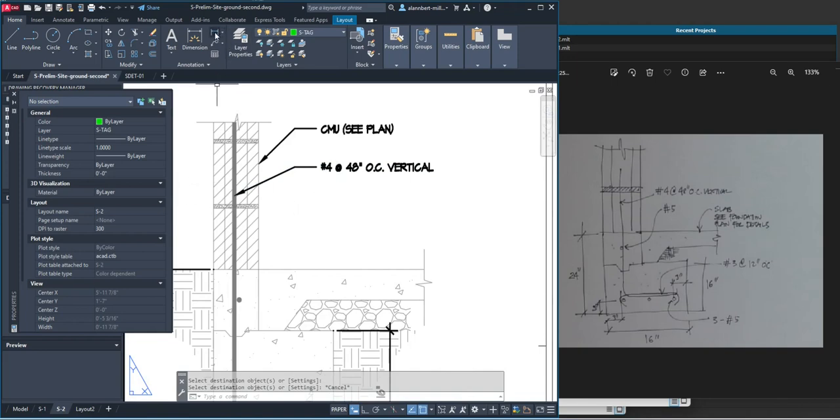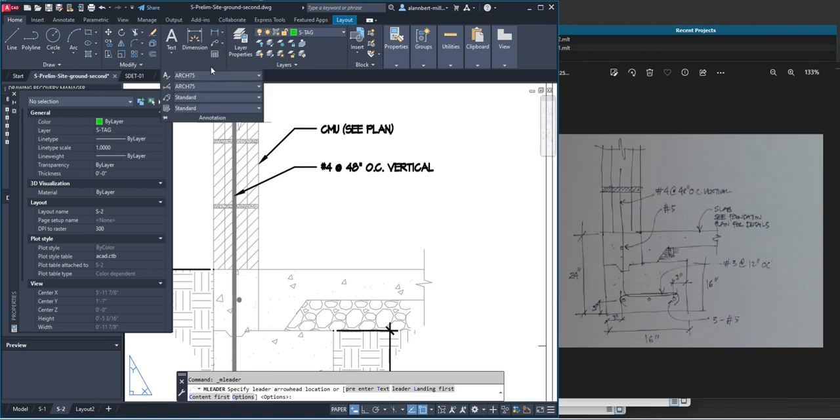When we click this one here, we can immediately change the style over here, and change the style to, or we have to create a style, so we can select it here. Okay, right now that's called standard. Okay, and we're just changing it here. Anyway, we can just do a match property, but you can always do a dimension style, just like you can do a leader style, just like you did on a dimension style.